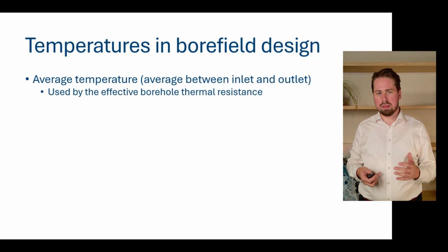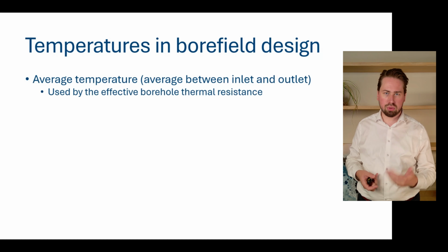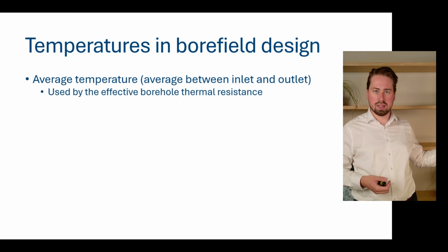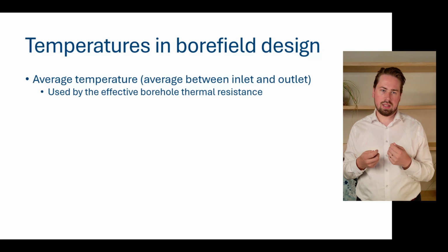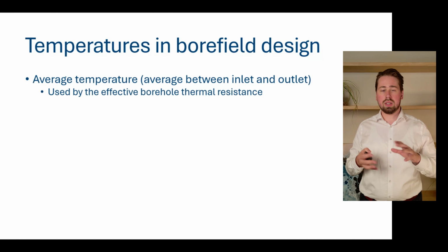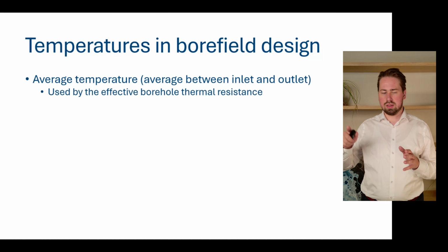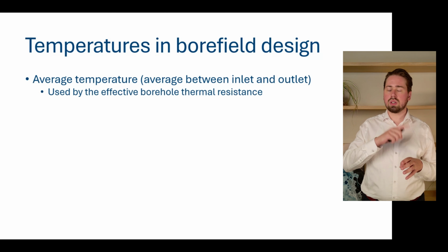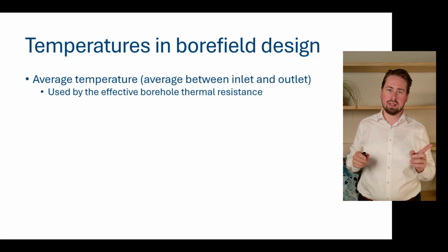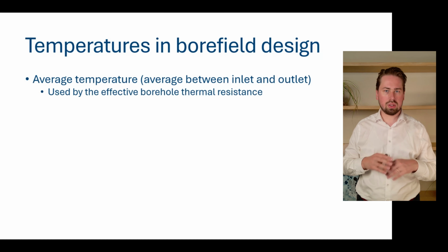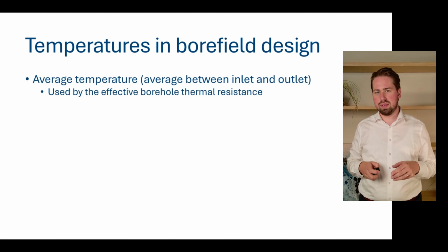And what is good about this temperature is that we do not care about flow rate directly. We do care about flow rate to get our Reynolds number and our turbulence and so forth, but we do not need it for the temperature calculation itself. We just use the average, so we do not care if we are, for example, working at 0 degrees in the borehole, 3 degrees out, or let's say 5 degrees in, minus 2 degrees out. It's all the same average fluid temperature. So it makes it really straightforward to work with.